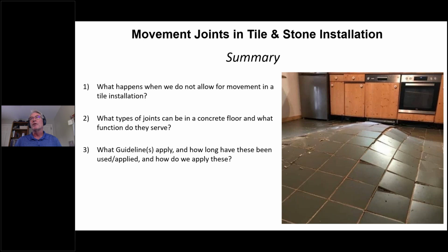Yeah, good. I'm glad you said that. Really good comment. But yeah, I can't stress enough, it has to be clean. Perfect. We do not want grout in that area and then caulk over it. We want it clean. Unfortunately, that's what we see a lot. We see not grout there so much, but mortar sticking up.